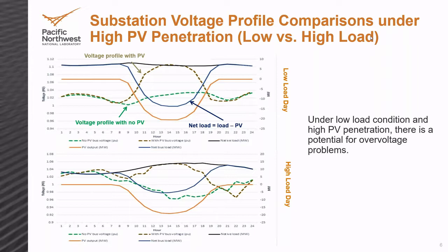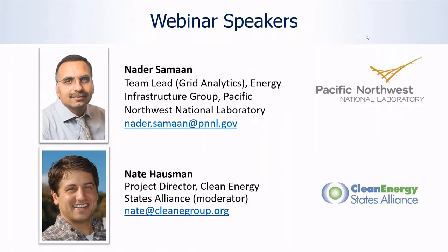So I think the issue here is what kind of arrangement needs to be made between the utility and the PV plant owner, especially for commercial projects of a few megawatts. Are they willing to let utilities control their smart inverters, and will they ask for a price for that? Or would it simply be part of the interconnection requirement? Like, if you give me control of your smart inverter, I'll do my best not to curtail your real power, but I'll control your active power to maintain certain voltage.